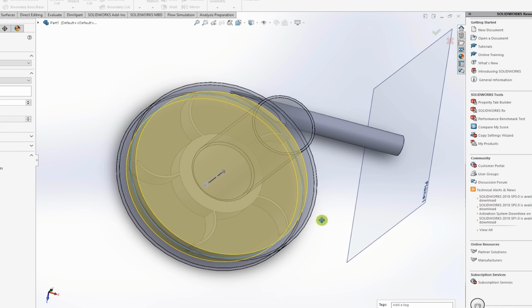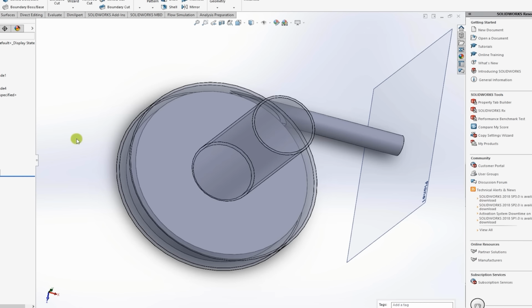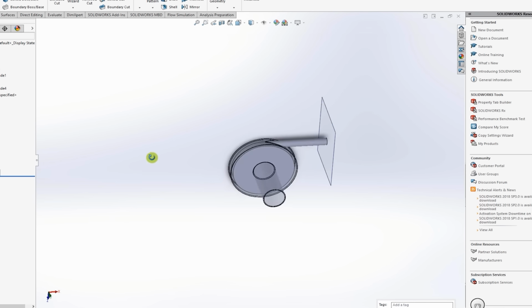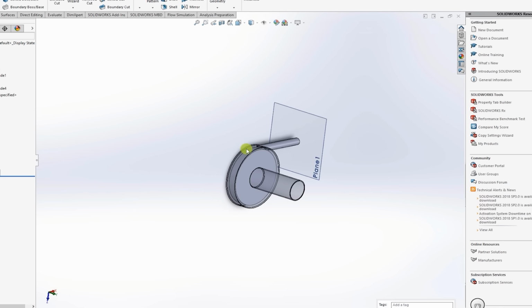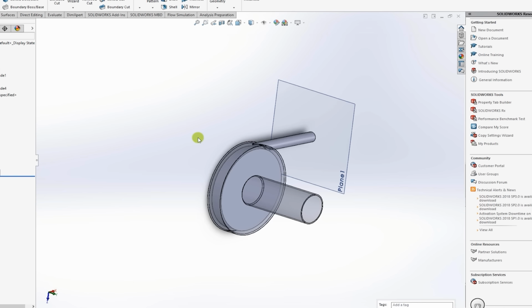Okay, so this is a very tricky step. You might get this wrong a couple of times. Do check the size of my extrusion, 0.011 meters, and also the radius that I had used for this zone creation so that you can recreate it. All right, so let's click OK, but before we do that, we need to make sure that merge results has been unchecked. So this is an important step. All right, so it looks like our CAD model is set up correctly.